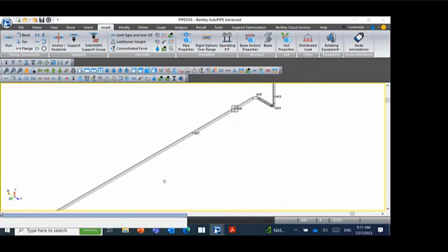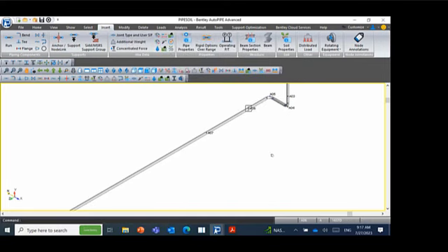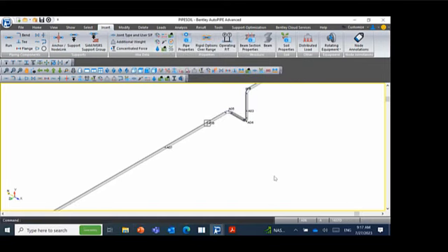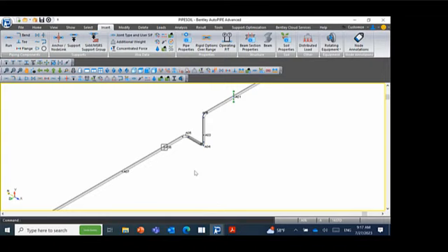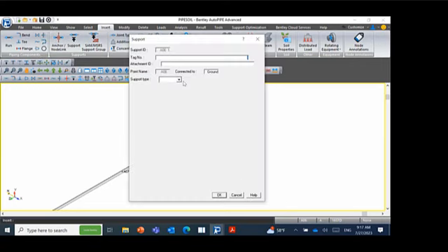So if you put many supports, and maybe supports in all directions, because the soil is an all-direction restriction, okay? When you have a buried pipe, you have all-direction restriction. You need to declare something like a spring or something like a stop with no gap.